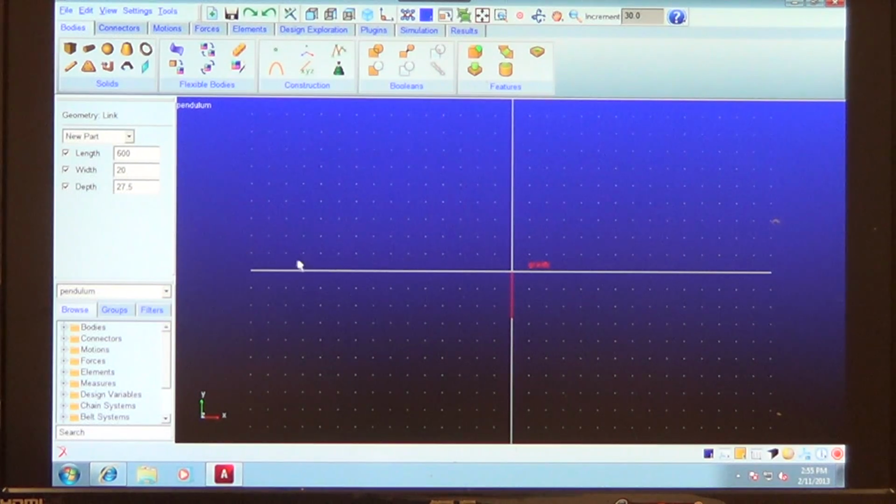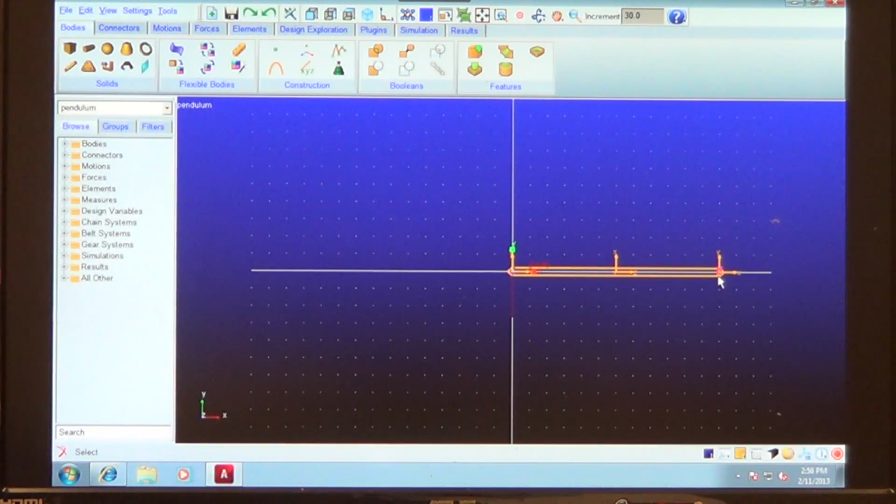And then what you need to do is position it, and select 2 points. So you click it here as your starting point, and you see the link becomes visible, and you make it horizontal and set it in the other point to position it horizontally.